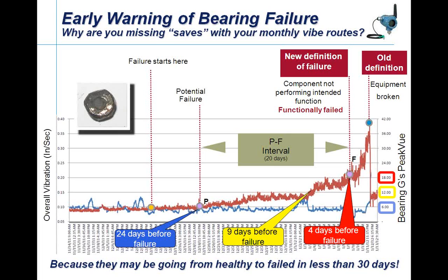That would create a less frequent measurement case. So you want to measure your data here at least 2 and a half times, in this case every 10 days, to be able to pick off this problem. And so I think that is where an application for monitoring beyond a route-based approach might apply.